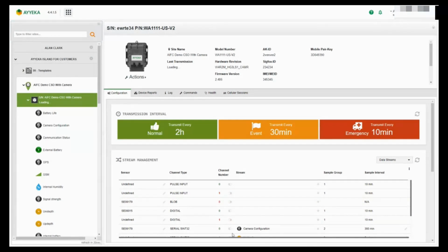The sampling generally doesn't take as much energy because the sampling is carried out in milliseconds, generally approximately 300 milliseconds for the sensor to wake up and take its sample. So we're not powering the sensor all the time. We're only powering the sensor for that very short burst every 10 minutes or every 20 minutes or every hour to actually wake up, take the sample, and everything goes back to sleep.